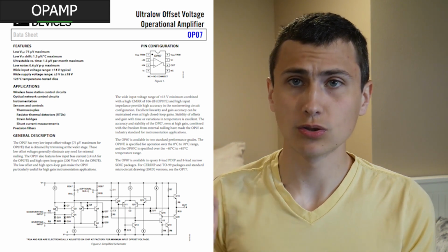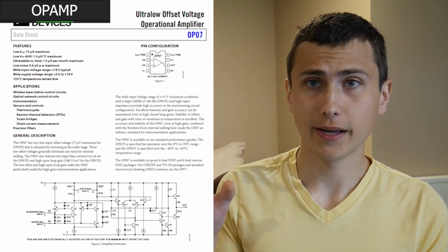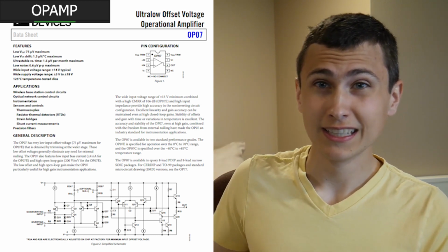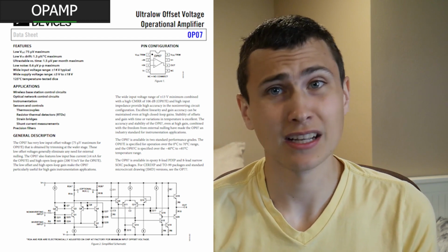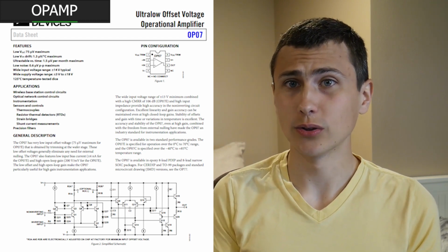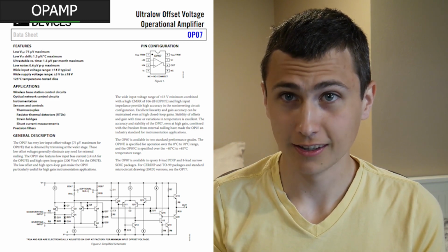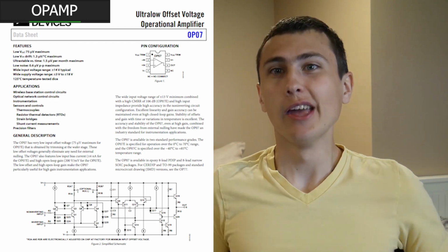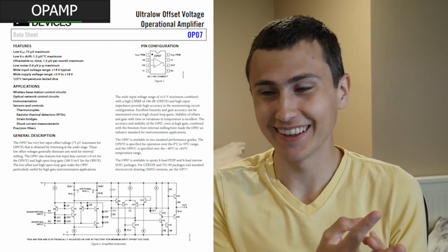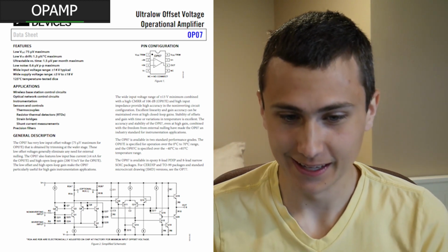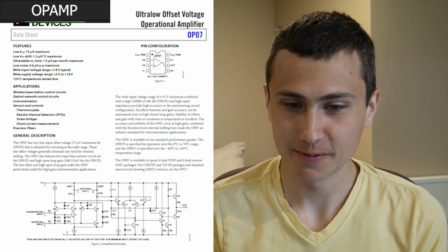We're going to need to make sure that the amount of gate capacitance in this FET isn't going to make the OpAmp unstable, because if we start to ring, that's not going to look good. That's not going to be that nice, clean electronic load that we're going for. That'll be a noisy, hot piece of garbage. Probably all of those things. It will be garbage, it will be hot, and it will be terrible. So we better not do that. Better not have that oscillation.